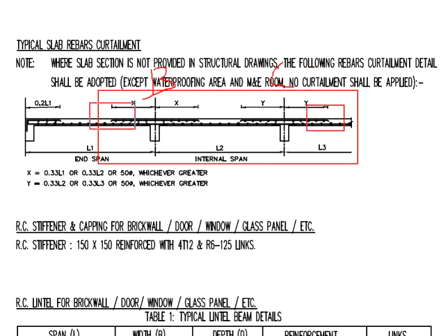You have adjacent slab. The arrangements of the reinforcement bar will be something like this. There will be top reinforcement bar, and this length will be 1350. Same here, and 1350.